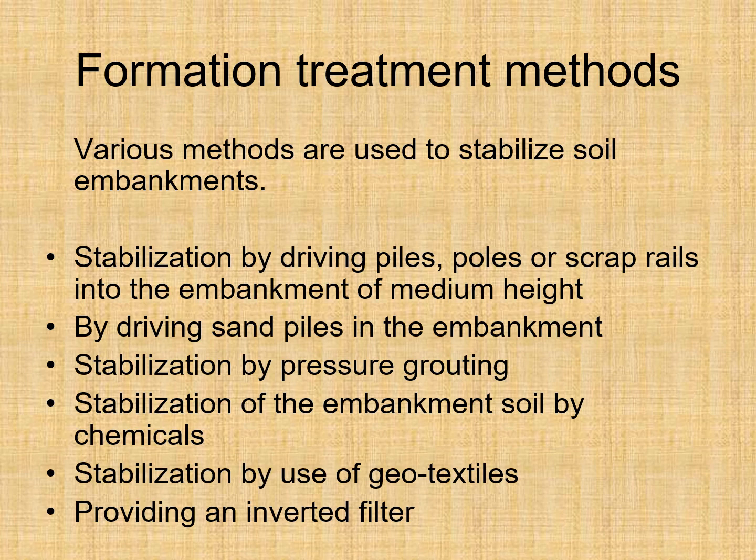Now, at the end of this file, you would find some formation treatment methods. So various methods are used to stabilize soil embankments. Stabilization by driving piles, poles or scrap rails into the embankment of medium height.